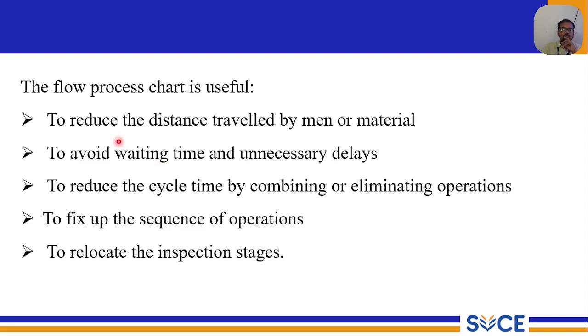So it helps you to reduce the distance traveled by the men or material, thereby reducing the overall fatigue of the worker. It also helps you to avoid waiting time, through which you can implement the concept of just in time, which in a nutshell is bringing the right product at the right time and at the right place. It also helps you to reduce unnecessary delay. Again, you can bring in the concept of reducing bottlenecks and starvation, and the overall cycle time can also be reduced. It also helps you to fix the sequence of operations and relocate the inspection stages.